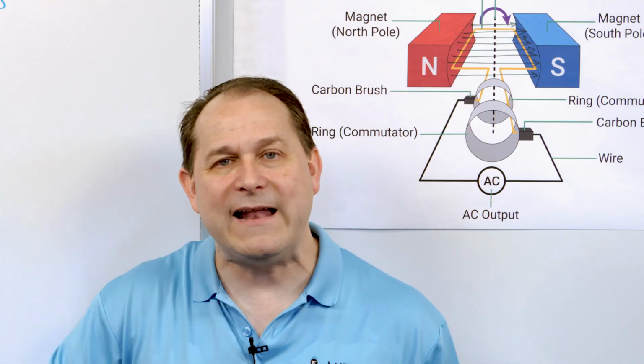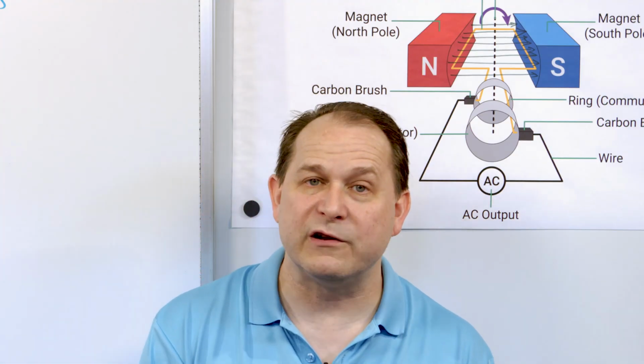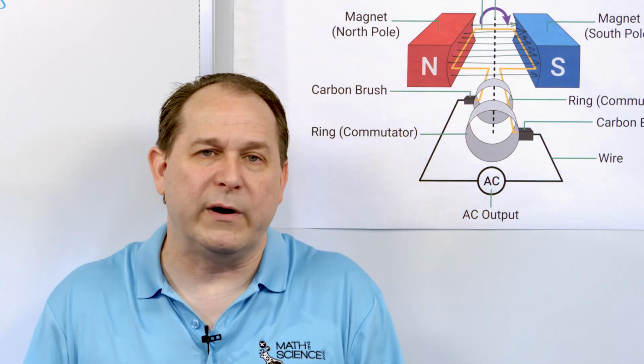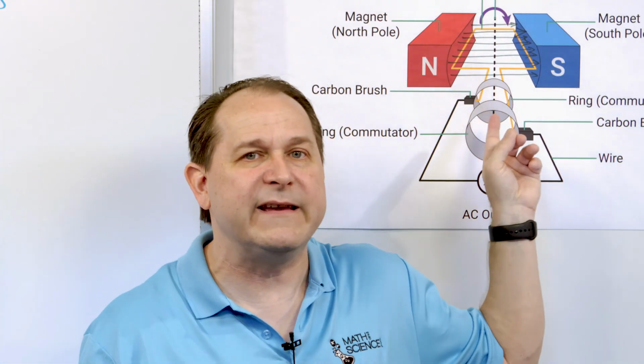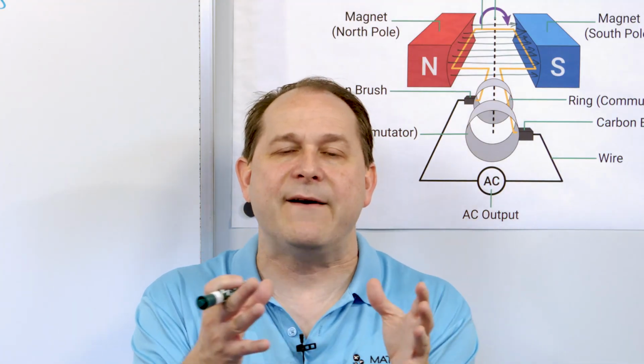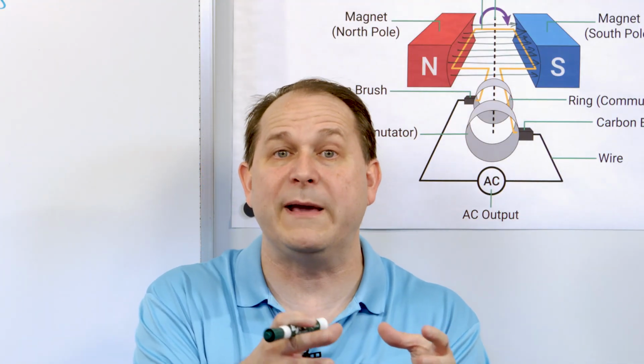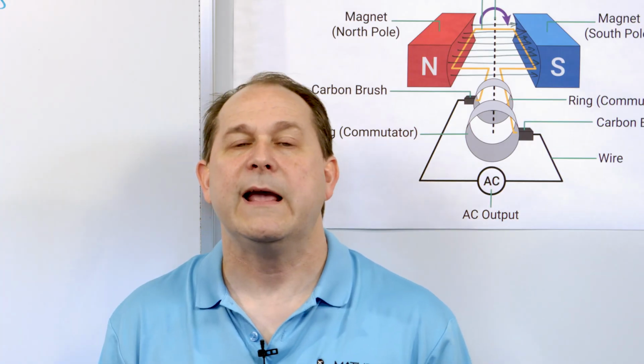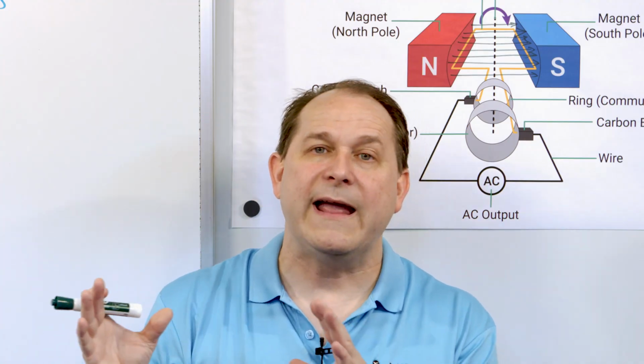a sine. And that is why the voltage that we get from generating electricity from this kind of method is a sinusoid. And because it's a sinusoid, we can use transformers to step up and down the voltage, because transformers, the same way this induction only works with something changing over time, you have to have AC electricity in order for transformers to be able to step up or down the voltage. All right, and that is why we have AC electricity so prominently in our houses, because we can generate it very easily using a system like this. We can step it up and step it down and transmit it over long distances without too many losses.